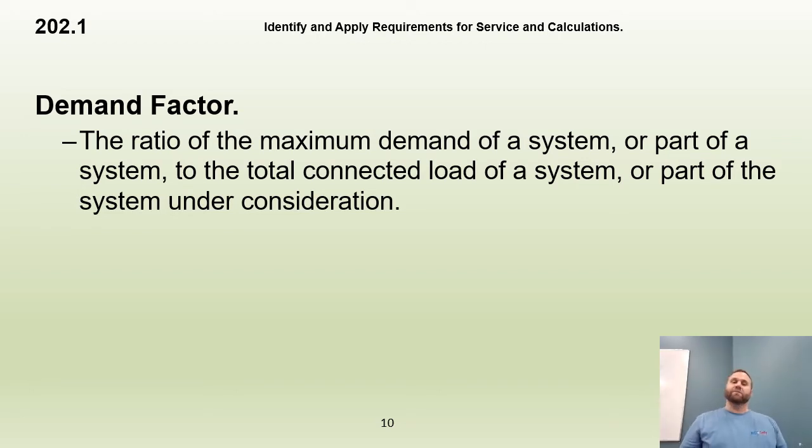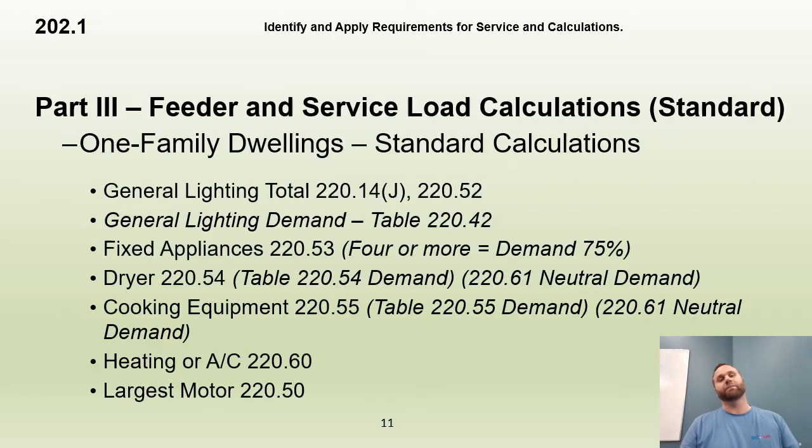So understand that going forward from this point on, when you hear me use the word demand or demand factor, know that we're shaving off from the total connected load the potential for using that entire load at 100% all the time, because we know we're not going to do that. We know we're not going to use everything 100% of the time. So hopefully that helps you in understanding demand factor a little bit.